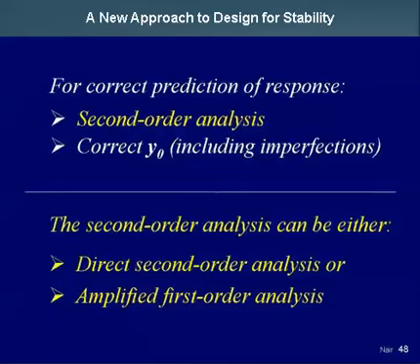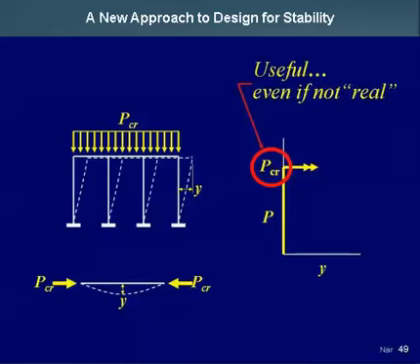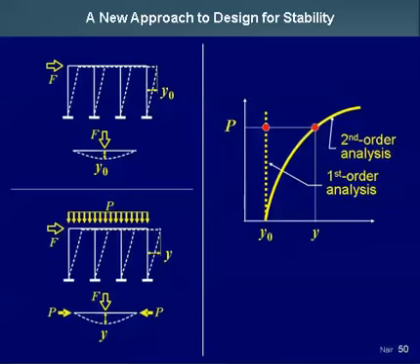Now, just to take a little detour here, what do I mean by second order analysis? A second order analysis can be either a direct second order analysis or so-called amplified first order analysis. What does that mean? Well, you remember this concept of a critical load, and I said it wasn't real, but it is useful, as we'll see in a moment.